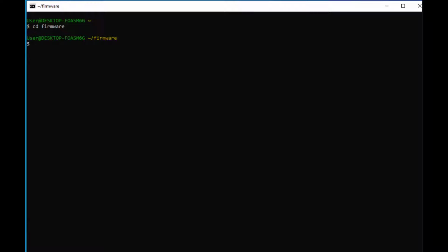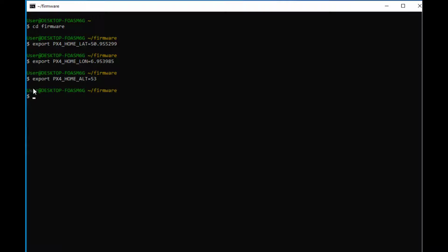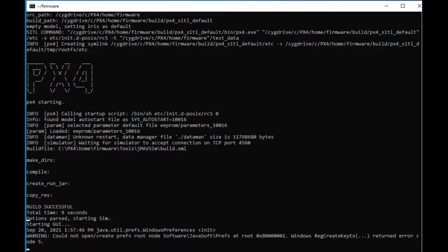Before we start jMAVSim, we need to tell the simulator where it is actually located. Else our drone might fly around half the globe, as we define a corridor with local coordinates with the app. So set latitude, longitude and altitude values close to your actual location. The distance to your location should be within the range value that we set later in the Python script. When all is set, we can start the simulator. This will take a while.